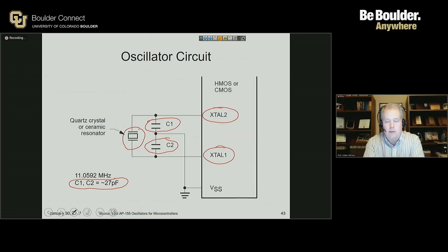These components should be placed close to the oscillator circuit inside the processor. So what we want is the external crystal and load capacitors to be located pretty close to the Xtal1 and Xtal2 pins on our device. If we put it a long ways away, now we start introducing larger inductance because of the loop areas involved, and that complicates our tuning of the network.